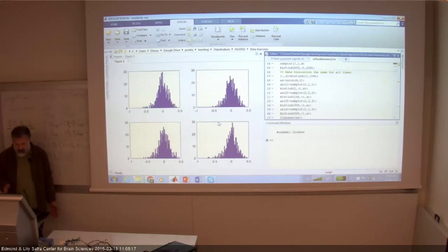So there's nothing dramatically different between the histograms at different time points. They are not quite Gaussian. Can you tell me why? What's in the shape that makes them not Gaussian? Yeah, they have a tendency to be a bit asymmetric, with the left tail a bit larger, heavier than the right tail. This is due to the spikes, and after filtering it will disappear completely. So as far as I'm concerned at this point, this is good enough to be called Gaussian.